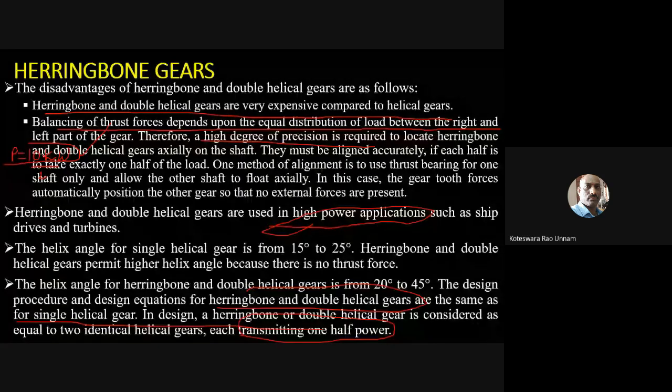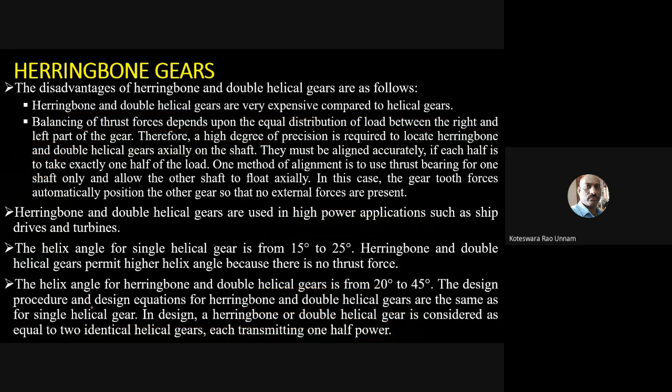Nothing that much great or important. The only difference is that these are used to eliminate the axial thrust forces in the shafts or shaft bearings. So that is the reason why we go for herringbone gears.